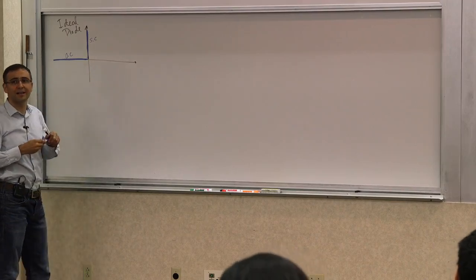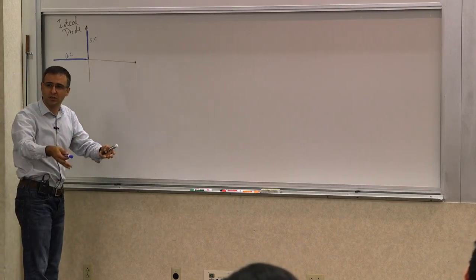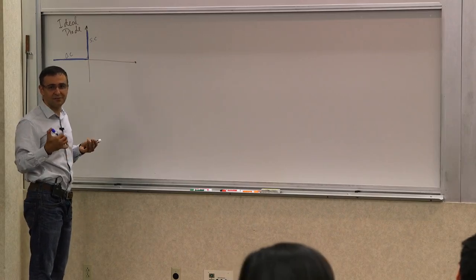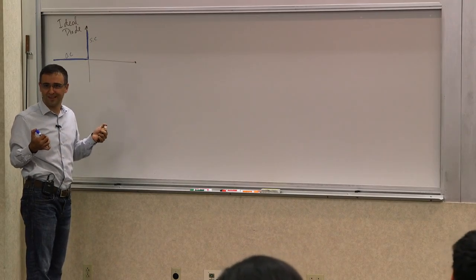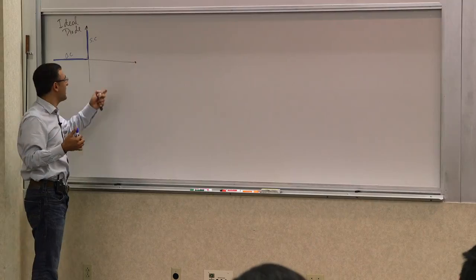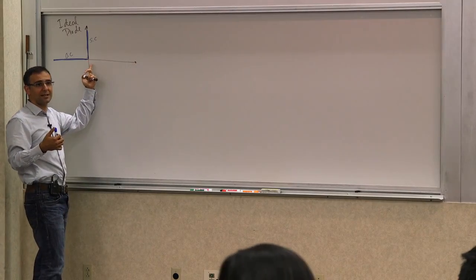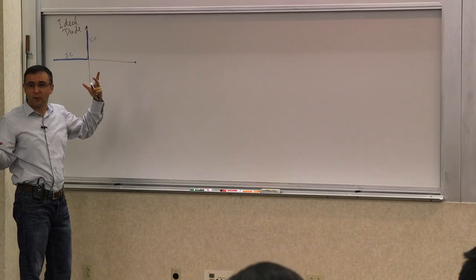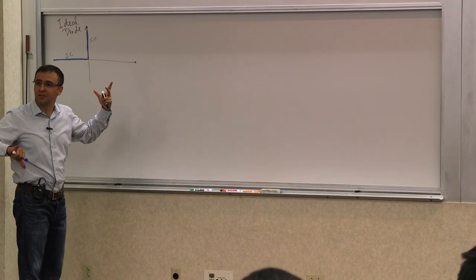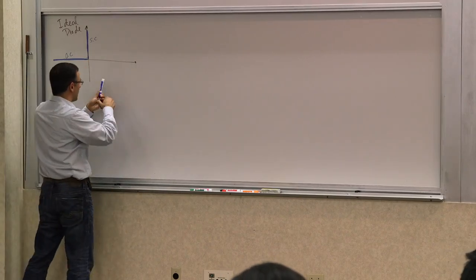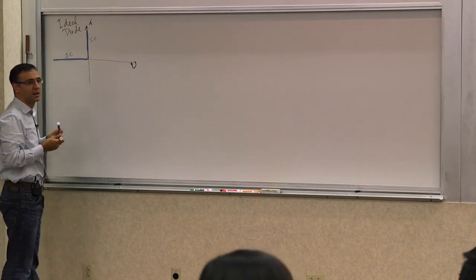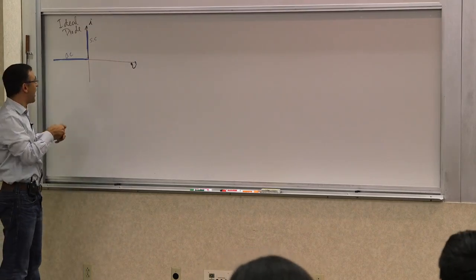If there's forward current, it's a short circuit. And there's a reason I'm saying it that way. Because you can't apply a 3-volt supply in the forward direction without things exploding, but you can apply it in the reverse, no problem. The voltage can be negative. So this is the voltage, and this is the current. This was the ideal diode.